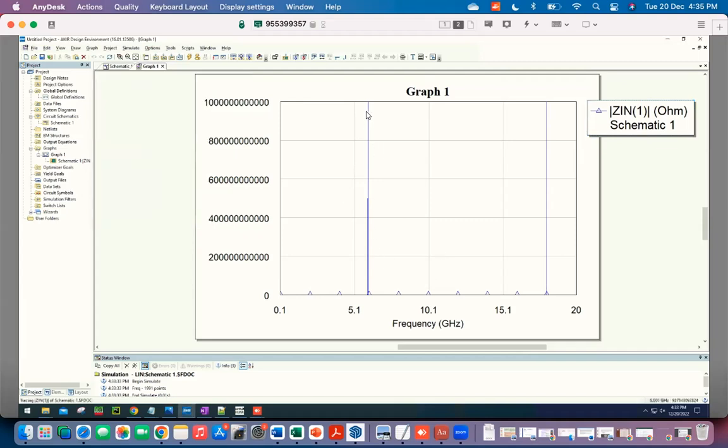But you can see the first one here is at 6 gigahertz, and the next one is at 8. This is the thing to note, because the next boundary condition in terms of the wavelength you can fit with one end shorted and one end open goes straight away to 3 times the frequency. So this is again something specific to a lambda by 4. In lambda by 2, it will just go to double.